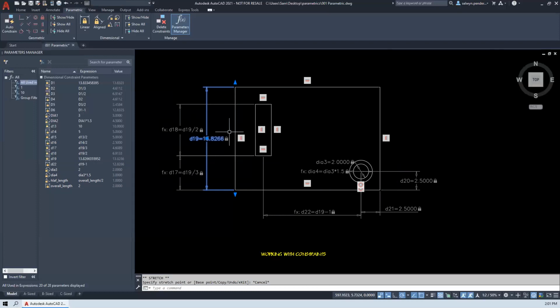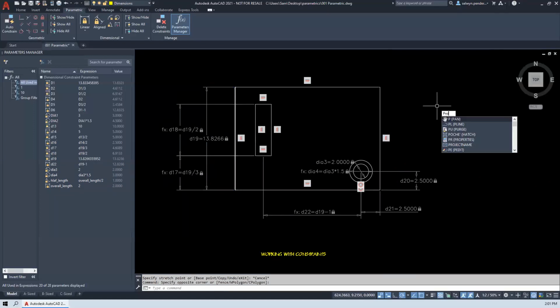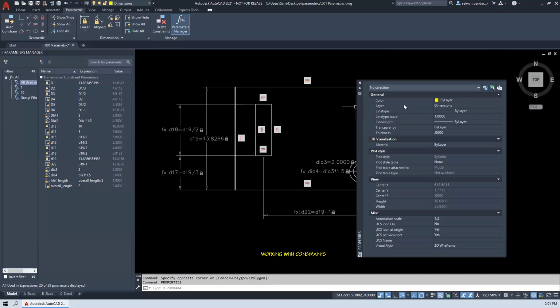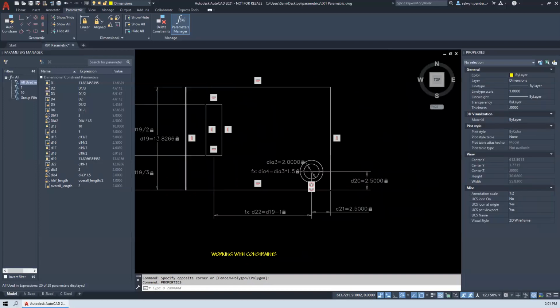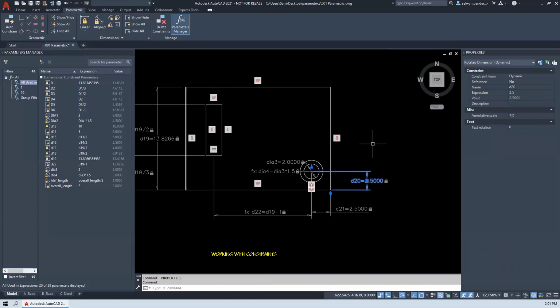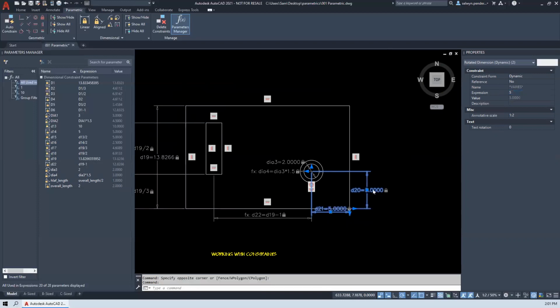No, look, the only other thing probably is just to turn on the AutoCAD properties panel, just so users can see that you've got the parameters manager to edit. You can double click to edit, but also the AutoCAD properties panel will let you type in and make similar changes to name and expression. So you can change it here. If I go 5, those 2 entries will change to 5. So it's now 5 units from the corner.